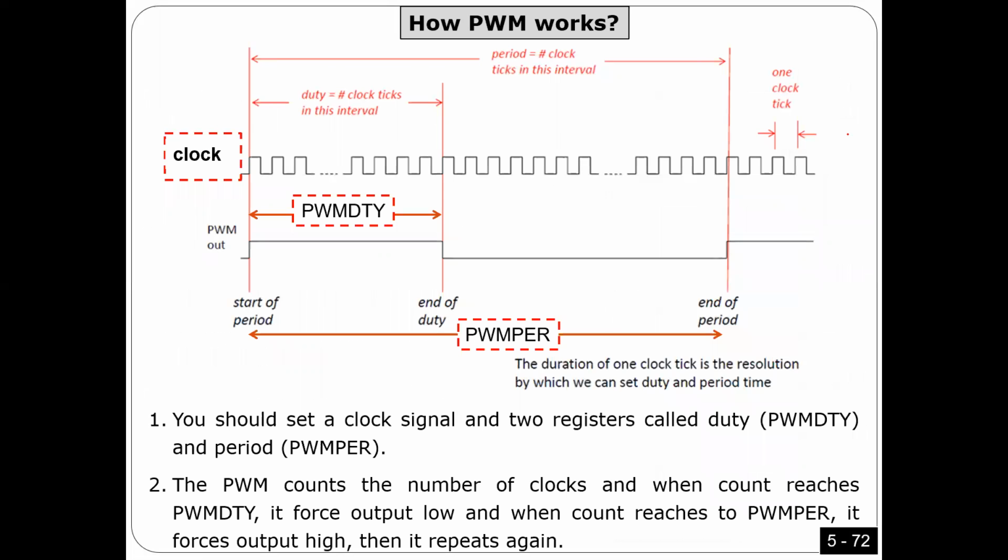Okay, how it works? I'm going to tell you how it works and the main idea here. Number one, we have a clock. I'm going to tell you later where this clock is coming from. But what I'm saying, we have a clock. Number two, every channel should have 2 registers, as you see here. One is called pulse width modulation period, and one is called pulse width modulation duty cycle. The duty cycle is telling you how big the high signal is, a number of cycles here.